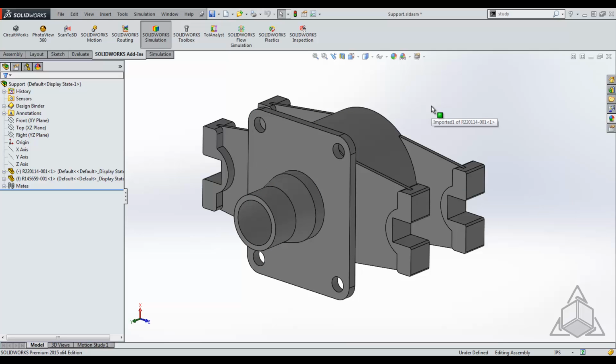Once simulation is on, you'll have access to add any command from simulation to these shortcut menus as well. You'll notice that my mouse gestures has been set up to create studies, run studies, and mesh parts. My S key in the graphics area has consolidated menus for creating studies, creating loads and restraints, adding forces, modifying connectors, and running particular studies.